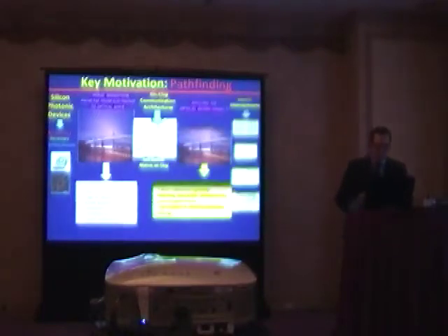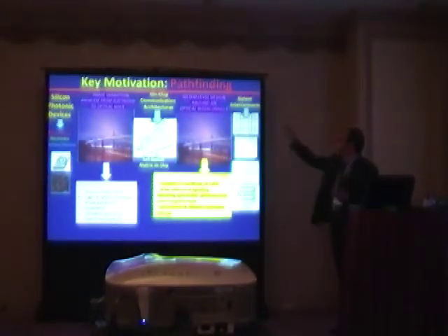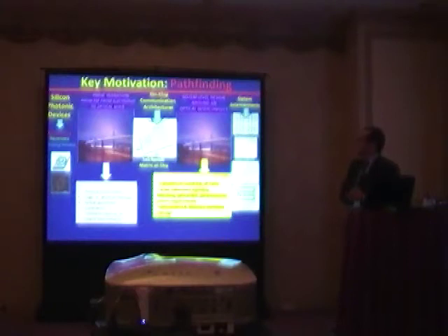Very far from here, there is another world, system interconnects, where there is a lot of research work on system-level design around optical interconnects. In fact, we have work proposed by Columbia University, we have Chameleon, and also work proposed by the University of Tehran, we have hierarchical rings, and also Corona and Firefly. In this specific case, the key features are scalability to 100 cores, cache coherency signaling, and so on.